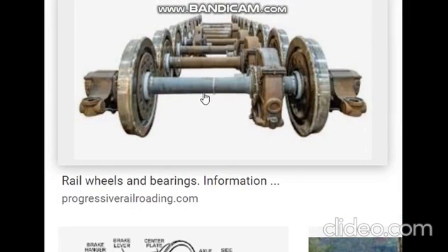What happens is, when it is traveling, it keeps on rotating. It may be sagging a little, so the upper fiber will be under compression and the lower fiber under tension. When it is rotating, the lower one comes up and the upper one goes down.